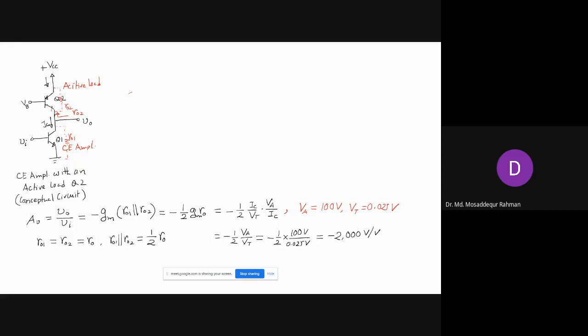If you use NPN and collector here, and then your emitter will be here, right? And arrow is pointing that way, right? Yes, sir. So here the current has to flow up, not down, right? And this does not work because here the current has to flow down, it has to flow up. So both will actually remain off. Okay, yes, sir. Got it, sir. Okay.